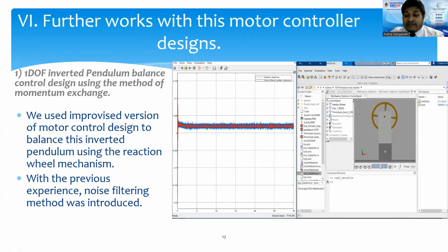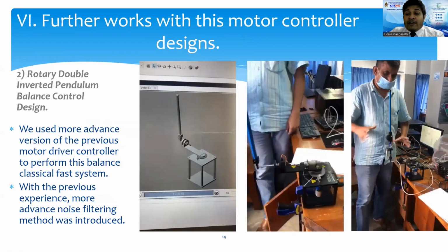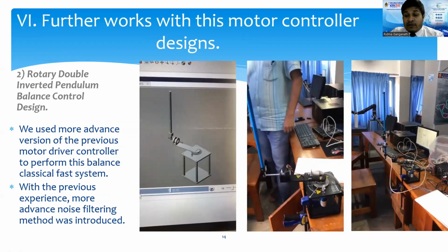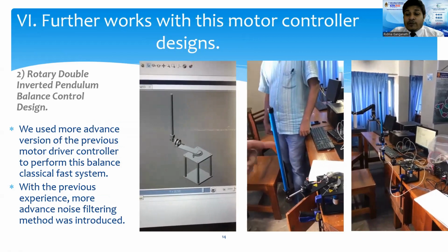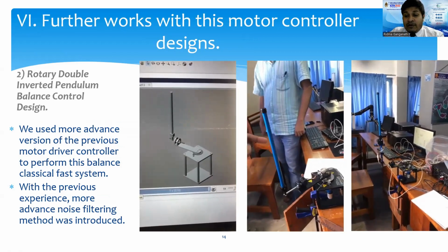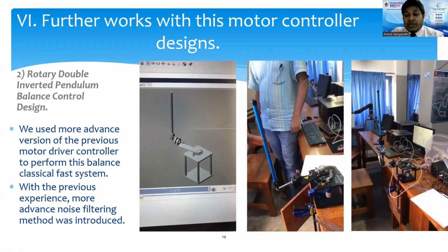With the previous experience regarding the noises, we improvised the theoretical approach to mitigate the measured noises. Then we used more advanced versions of motion control designs to implement the rotary inverted pendulum balance controller and get steady state results. As you can see, there are a lot of things to learn about motor controlling, and it is always good to read about the basic fundamentals regarding motor controlling during the undergraduate period.